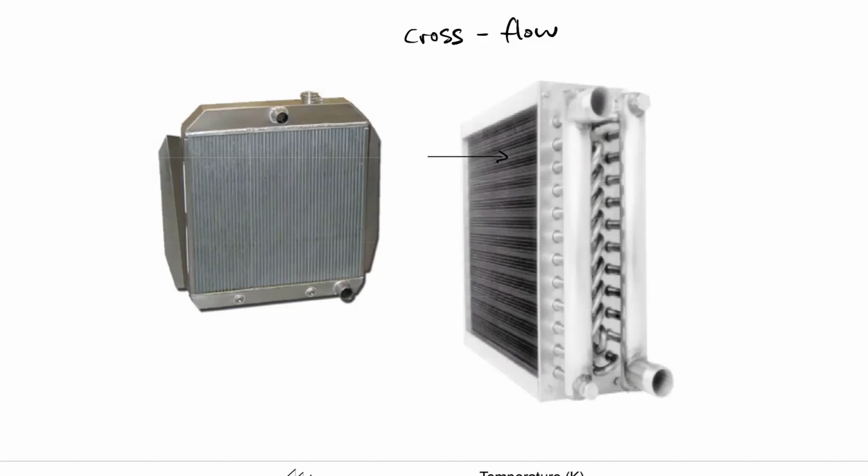Air is not a very good heat transfer fluid. It actually kind of sucks. So on the air side, the worst side, you put all the surface area. You've got these fins going into it. You're doing everything you can to extract as much heat out of that fluid as you can. And then on the other side over here, we have our refrigerant or water or whatever it is. That is actually a pretty good heat transfer fluid, so you just have it going through tubes. It's not limiting the rate of heat transfer, it's the air that's limiting. This is something you'll see when there's a big mismatch between the thermal quality of the two fluids that are trying to transfer heat.